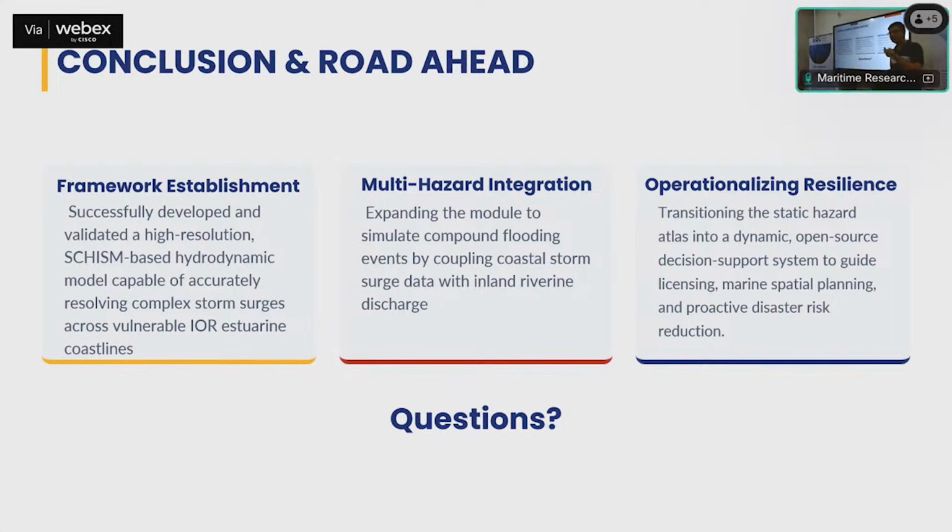Currently, I am simulating a model for the entire Bay of Bengal region. The resolution is variable because our coastlines are so intricate. That's why I use the flexible mesh, so that it changes the data as per the intricacies of the coastline, so that the entire coastline is captured. I have not exactly fixed a particular length for this data.